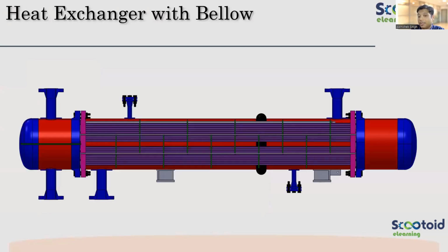So if that is the case, then for a fixed tube sheet, I need to provide bellows to take care of the thermal expansion. Because once I have a bellow, the shell will expand freely, based on how much the tubes want to expand. The bellow will take care of that. Deepak, it's bending for the tube sheet, buckling for the tubes.